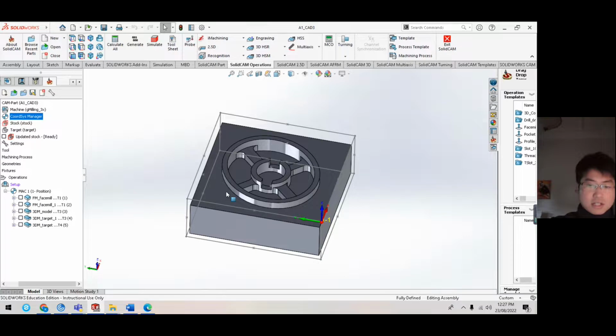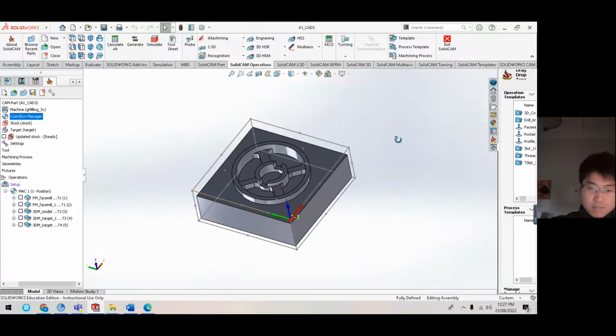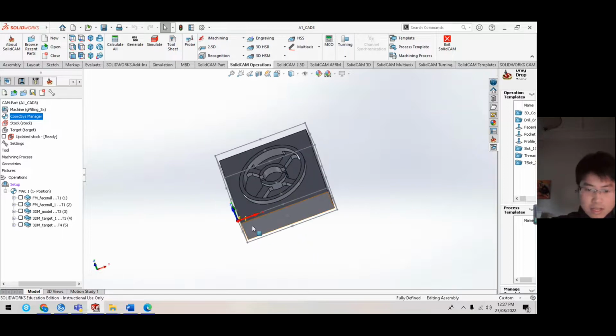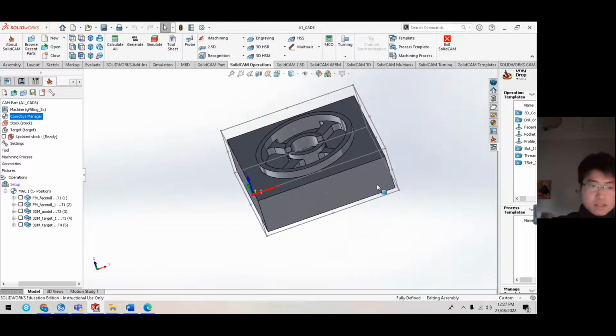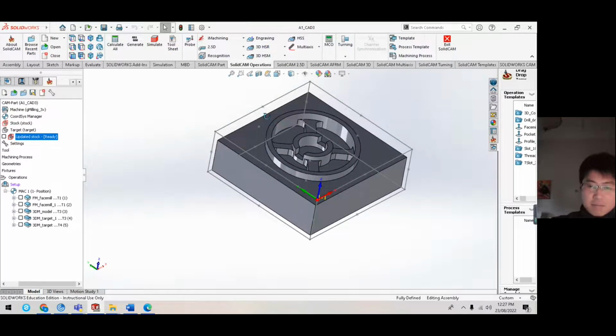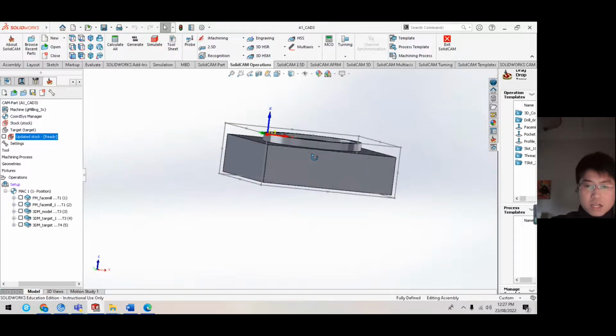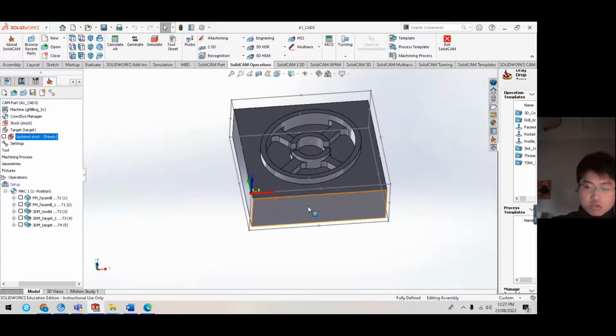Then for the coordinate system, we also choose the bottom left corner as the datum point, lying here. Then, as in the last CAD model, because this one is a rectangular block, we need to choose two small rectangular blocks on both sides to hold and lock this one stably. Then we will proceed to the next step.